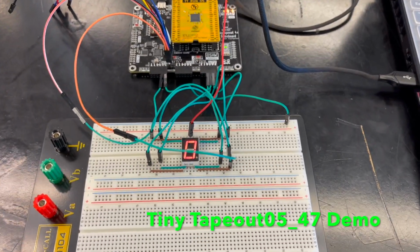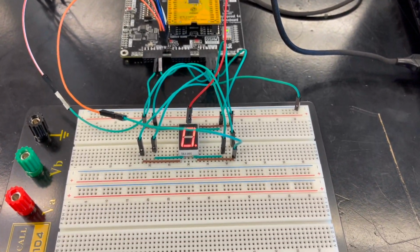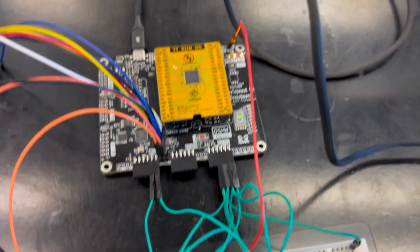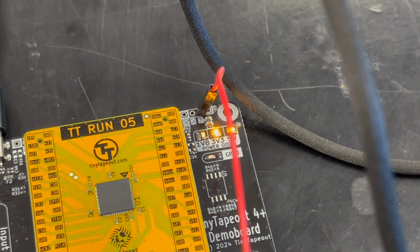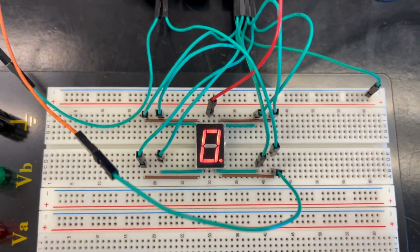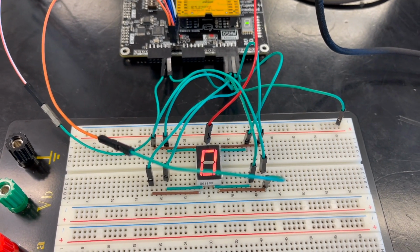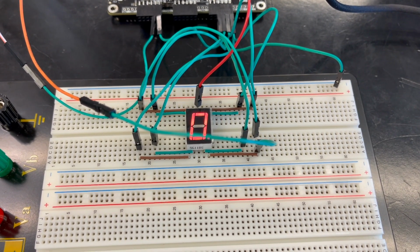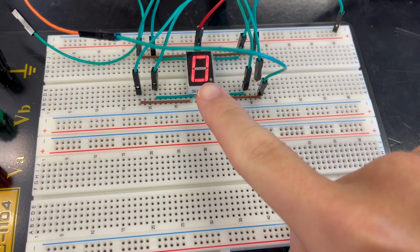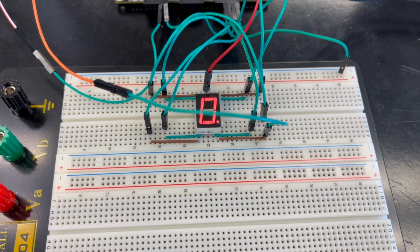This is the actual breadboard and wire connection from the board to a 7-segment display. For the power source, I connected to the 1.8 volt outputs from the board and connected to the COM port on the 7 segments. And the rest of the connections from the output are directly connected to the 7-segment display. For the decimal points over here, that's the clock cycle. So you can see it turning on and off.